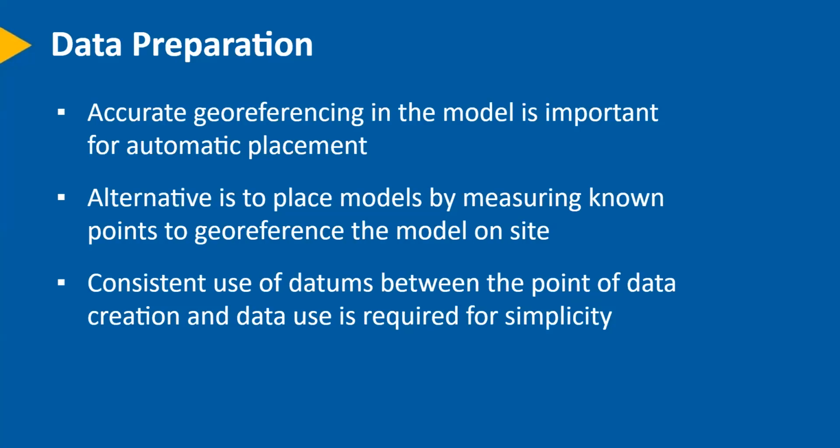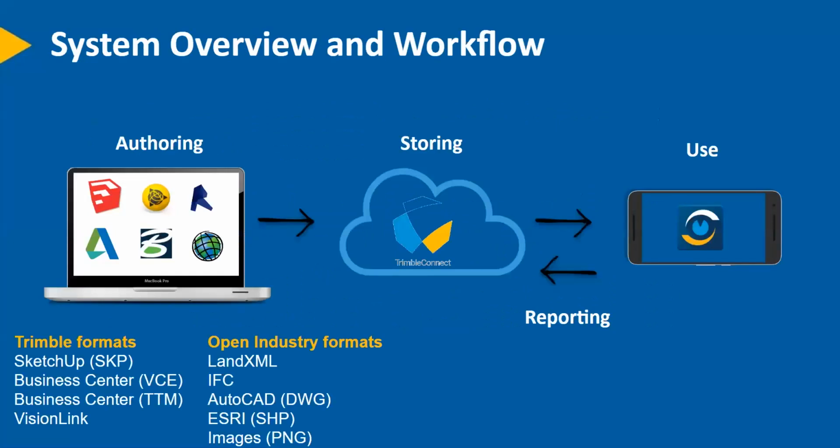And then also, for those of us in the GIS world and the survey world, the consistent use of datums is vitally important to the success of data use in the field, especially for augmented reality. Visualizing a model referenced to NAD83, the current realization of NAD83, to a real-time source for GNSS that's referenced to WGS84. Both are accurate, but are not relatively accurate. So data management needs to take into consideration the use of datums.